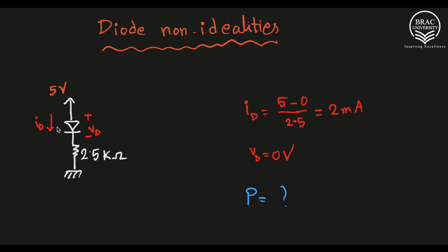So if you remember from the last lecture, since this voltage is positive and this voltage is zero, the current will try to flow in this direction, and the diode will allow all such currents. Since it is an ideal diode, we will replace it using a short circuit.